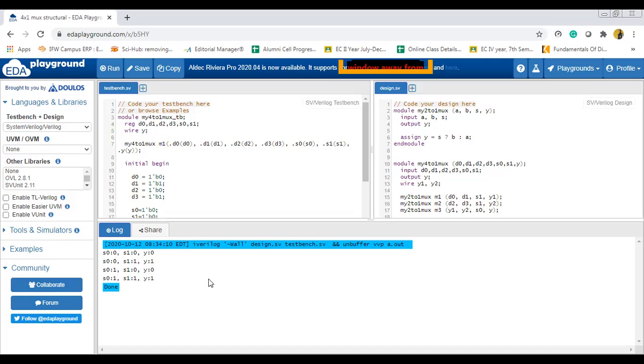So this is the simulation result of our design, and if you want to display the simulation result using the waveform, for that two more commands are required to be inserted, and these commands are the $dumpfile command and the $dumpvars command. A .vcd file is required to dump to obtain the waveform, and $dumpvars(1) means the one level of hierarchy we want to simulate.